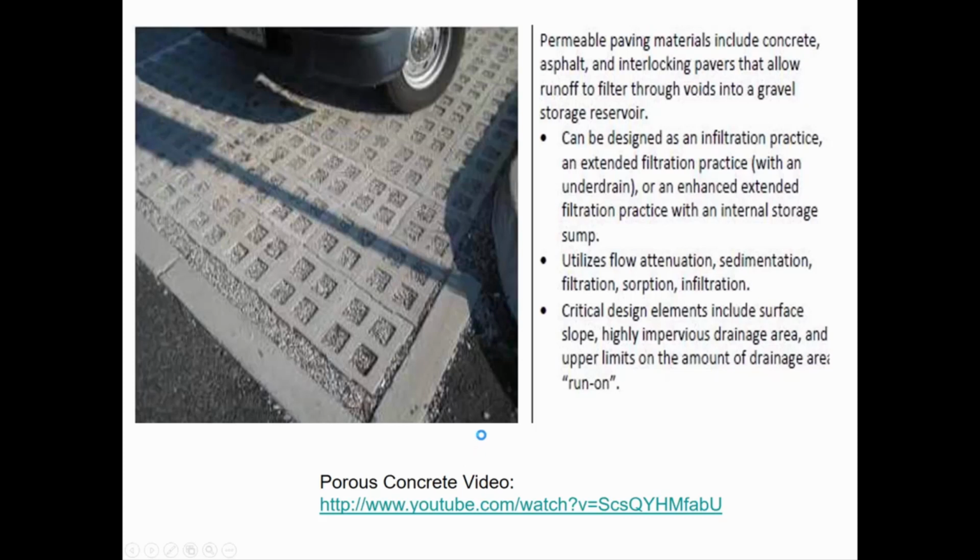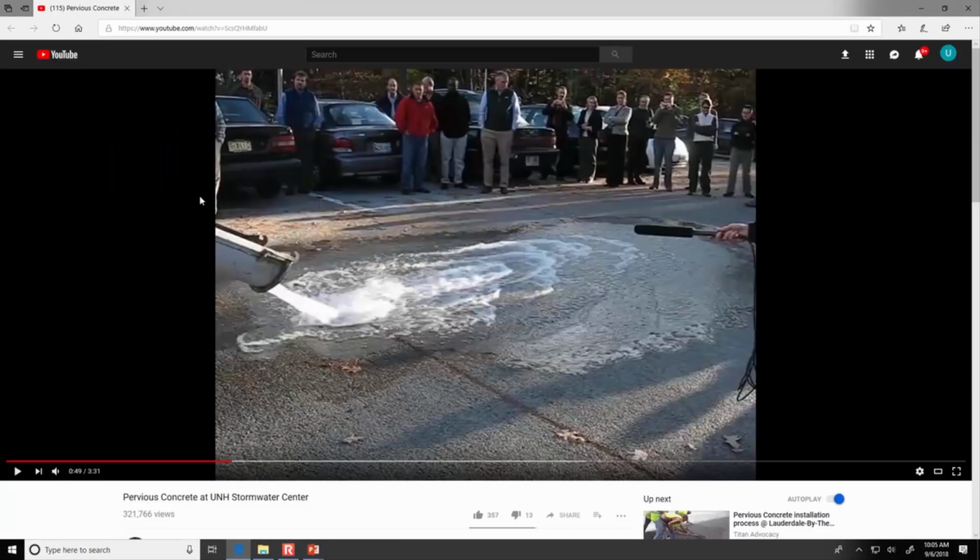And speaking of concrete, let's see if this YouTube video is still up. It shows some porous concrete. Because if you think about it, if the subgrade beneath the concrete isn't well drained, if there's water backing up and it freezes, it's just going to break that apart, no problem. So I think the key to good porous concrete is to have some slope to it and to have big pieces of gravel, like a thick gravel layer underneath, so that the water can really move through and get out before it freezes.